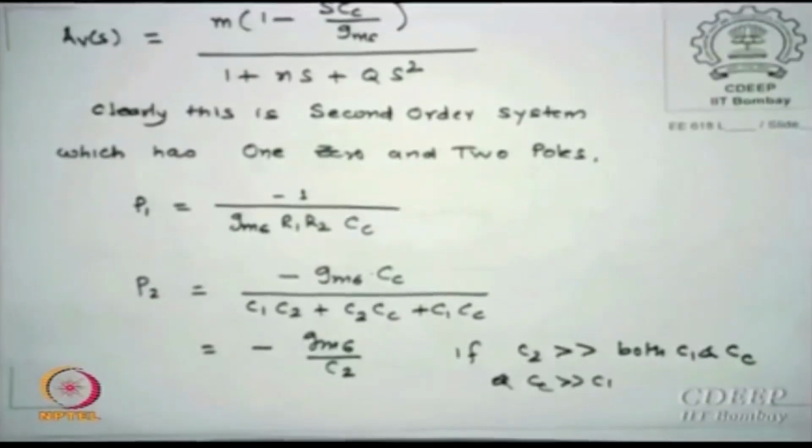So how do you calculate phase margin for this? I have figured out phi m is equal to 180 minus the phase of each of these, P1, P2 and Z. But what will be the phase of Z? Plus 45 degrees, that is minus 45 degrees. So what we do is tan inverse of minus is minus of tan inverse. Taking advantage of that, we will flip it, W by Z becomes Z by W, we will invert it. So let us see it now. Is that okay? Has everyone written it down?